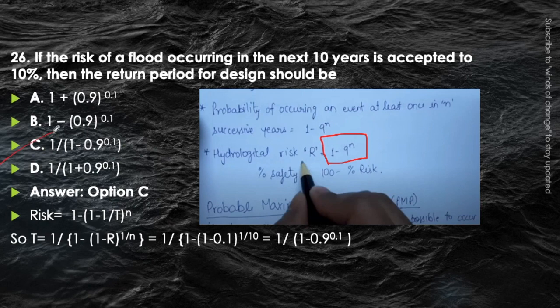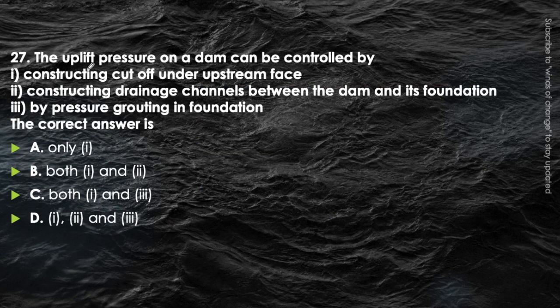Moving on to next question. The uplift pressure on the dam can be controlled by constructing cutoff under upstream face, constructing drainage channels between the dam and its foundation, by pressure grouting in foundation. The correct answer will be, think about it. Uplift pressure is from the bottom of the dam. Now this can be controlled by all of these, that is first, second and third.